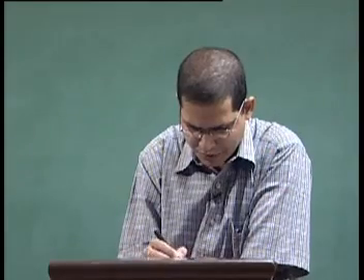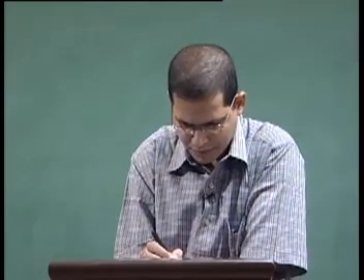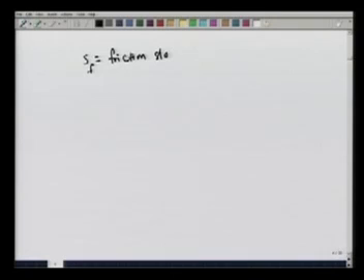So, we will study here the numerical solution to these equations, but before that let me explain this Sf, how one will estimate the Sf. Sf is the friction slope and it should be estimated by some resistance relationship, for example, Manning's equation.